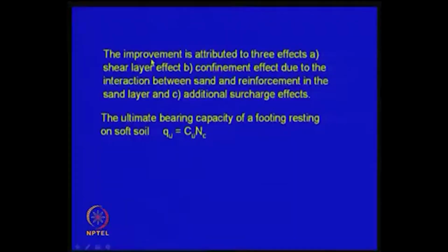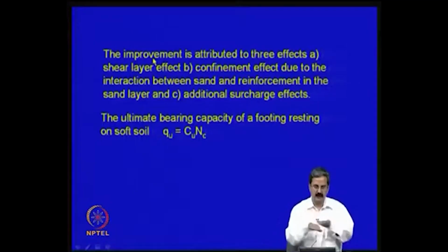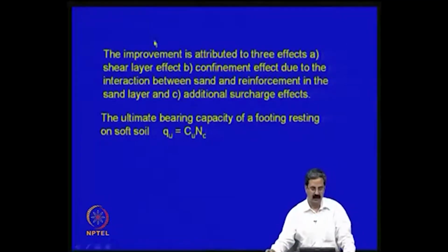So we can improve the soft soil bearing capacity by putting a sand layer and also some reinforcement in between, and we say that there are 3 effects that will help us. One is a shear layer effect, the second one is a confinement effect due to the interaction between the sand and reinforcement in the sand layer, and additional surcharge effects, right.